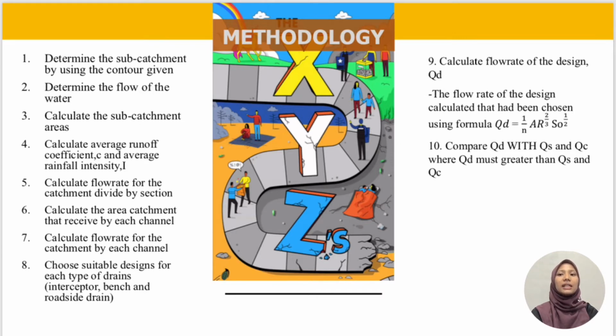The rainfall intensity, which is I, is typically taken from intensity duration frequency curve for rainfall event in the geographical region of interest. The duration is usually equivalent to the time of concentration of the drainage area. The equation application is simple when analysis is prepared by spreadsheet.